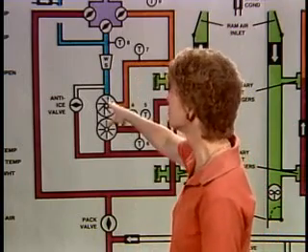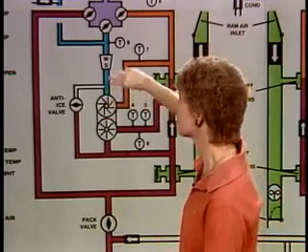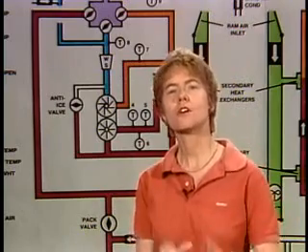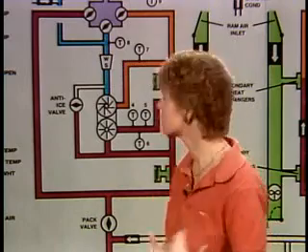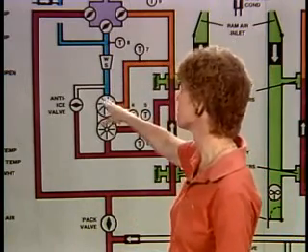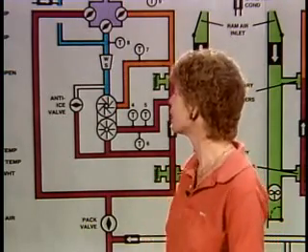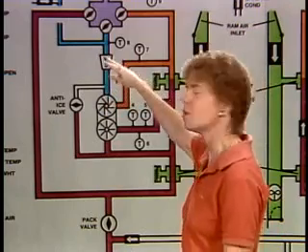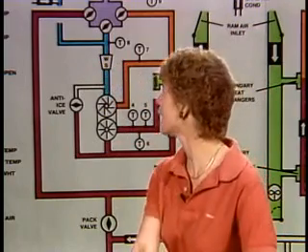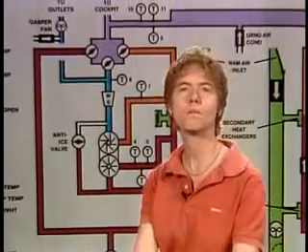When that air moves through this expansion turbine, it cools off very quickly, and that's what provides the cold air for the cabin. So the air in the expansion turbine undergoes a pressure drop and therefore a temperature drop when the system is operating. As it goes through this expansion turbine, you get both a pressure and temperature drop, and that's what gives you the cold air. And from there, it goes on to a water separator to get the water out, and after it goes through the water separator, then it goes into a mix valve.